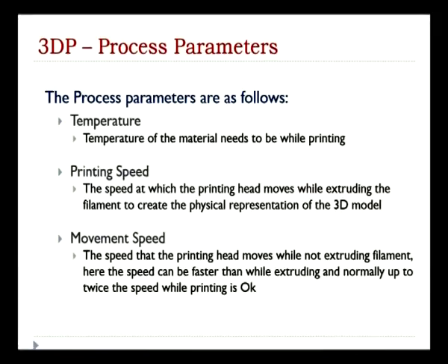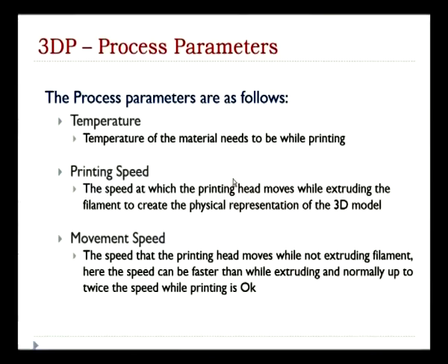Again, the temperature. Particularly while printing, you can see we don't have any closed atmosphere. We are using an open-ended area. So the temperature has to be optimally maintained within the delivery unit itself, right? It may be a binder, or it may be a solid or semi-solid, whatever the case. The binder itself should have a sufficient temperature controlling unit, or otherwise it will lead to material distortion at any time, right? So this really plays a vital role, because here that is the only area to control the temperature.